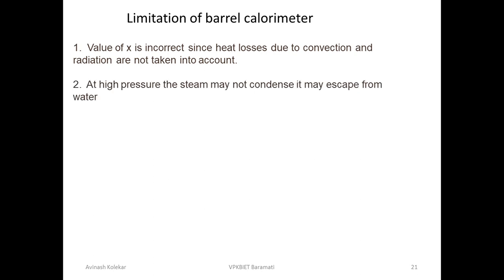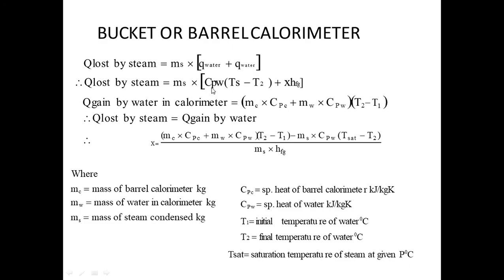That is the first limitation. And the second limitation is that suppose we have very high pressure. Suppose the steam is at high pressure, then what will happen? It will not condense, okay, it will not condense, and it will escape from the water. So due to that, whatever equation we are using is not going to be correct. It may go wrong, because it will not condense, but will remain as steam only.